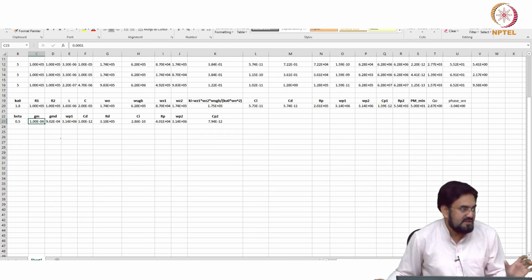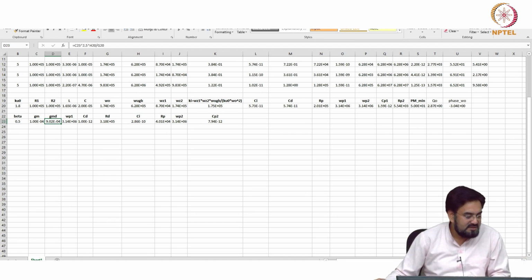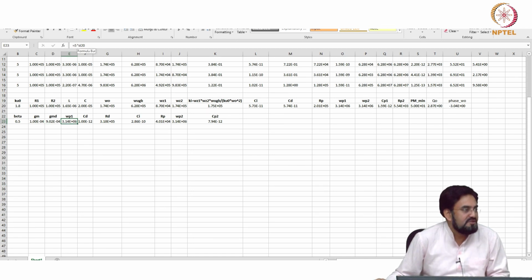GM by default you can choose some value, 100 micro, 1 milli, whatever, that will decide here. GMD you will also get from there. Omega P1 is nothing but that pole, so I am keeping that at 5 times of UGB. And then CD.